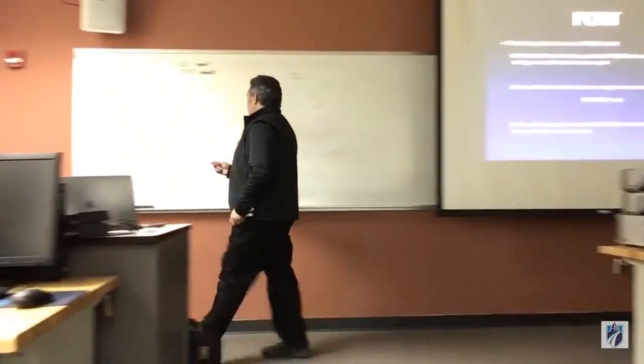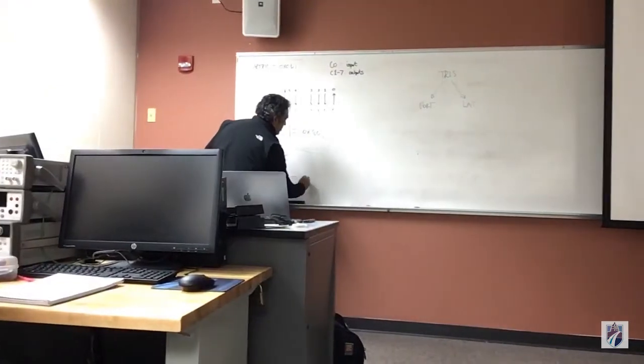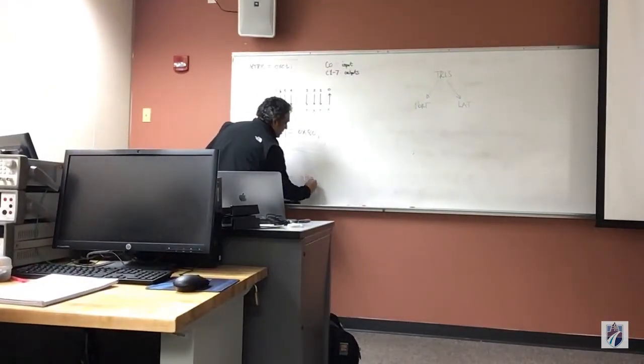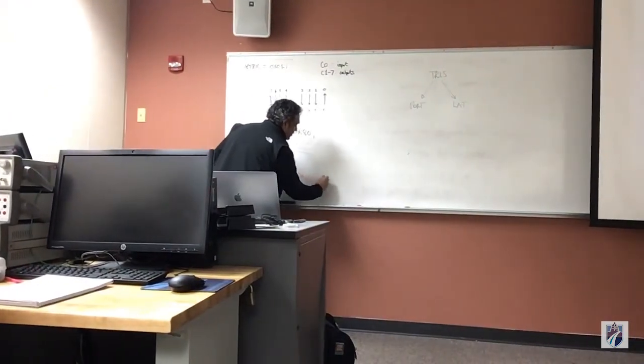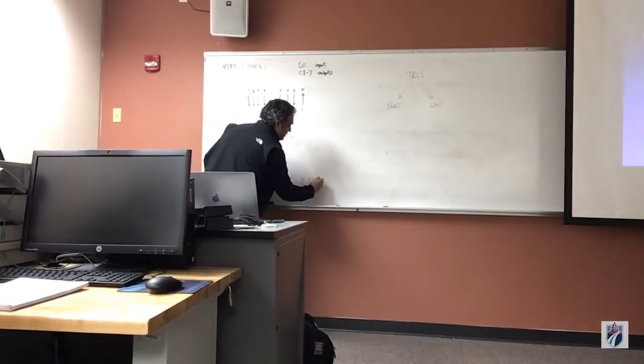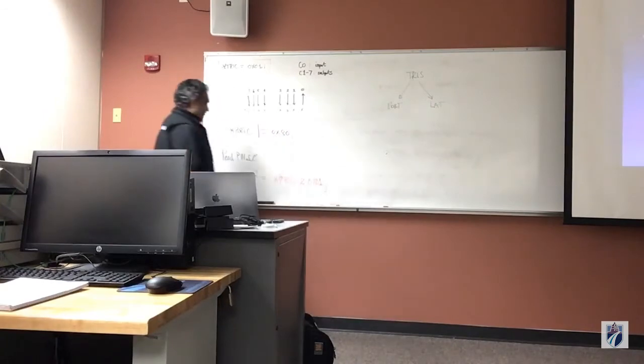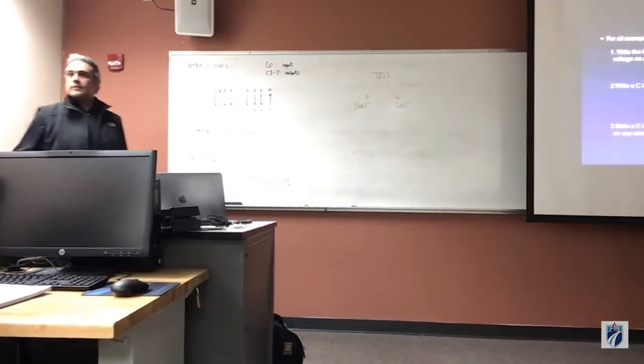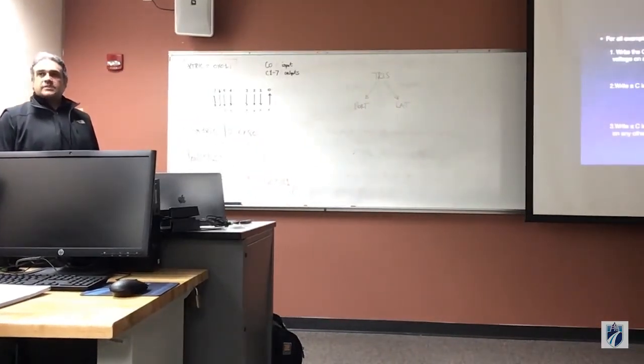So we're going to do input equals, and then I'm going to use the port C, and then I'm going to read the least significant bit. Right? See that?